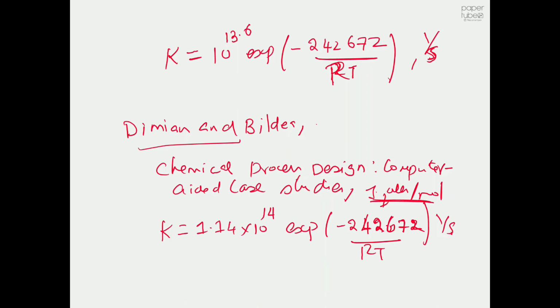Direct chlorination is at low temperature, 60 degrees centigrade, near atmospheric pressure, 1.5 atmosphere. Oxychlorination is at slightly higher temperature, I think 235 degrees centigrade, and 4 atmospheres. And the pyrolysis we are going to perform at very high temperature, around 550 degrees centigrade, and high pressure, 26 atmospheres.